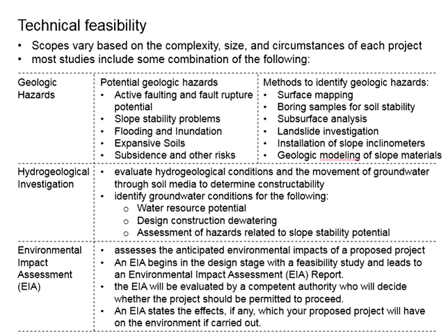Now, if the development is at the urban area, where there are existing nearby developed areas, rapid and large-scale dewatering can lead to significant settlement that may also affect the surrounding buildings. This needs to be evaluated in order to identify the potential implications to the nearby buildings before the project is being carried out. Next is the environmental impact assessment.